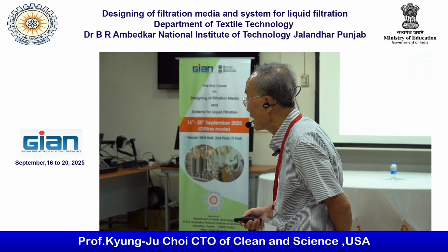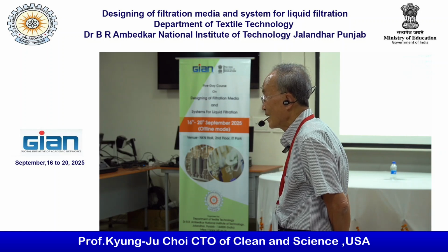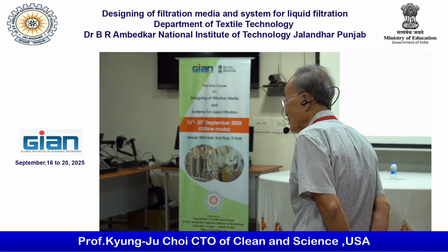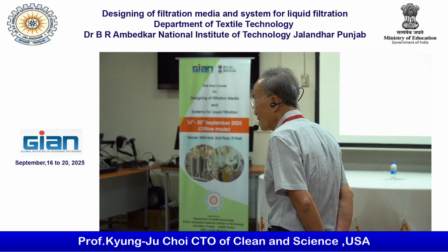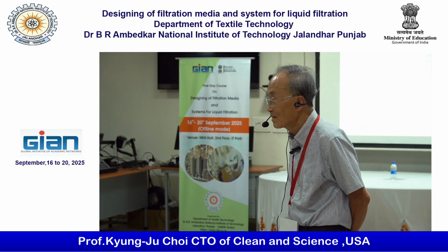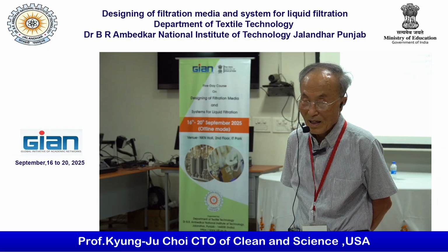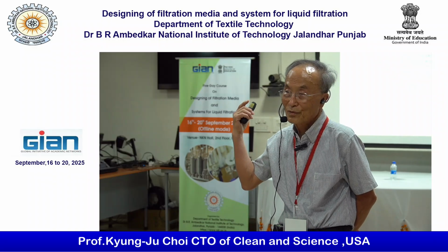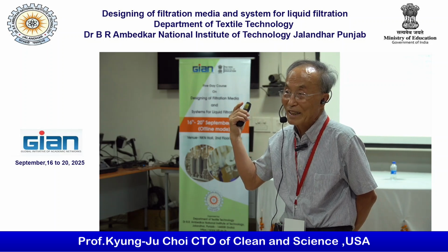Another point is that with water, you have to see whether the fiber swells in water. If there is swelling, then obviously the pore structure will change. During the measurement, that also should be taken care of. If you are working with polyester, it will not swell. If you are going for cotton fiber, it will swell. That void will change. So this is what I do. Actually, not I, my lab people are doing it this way.